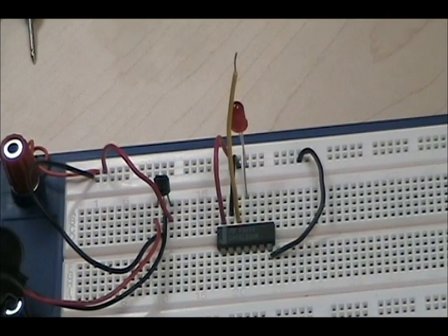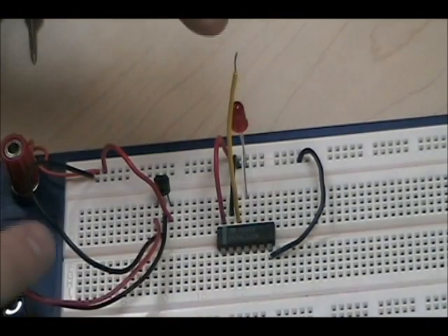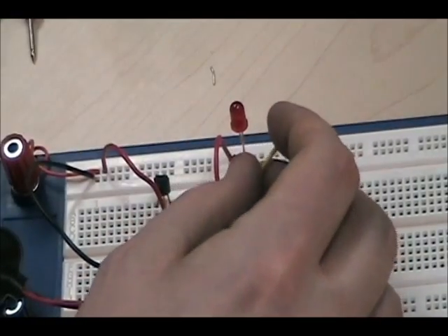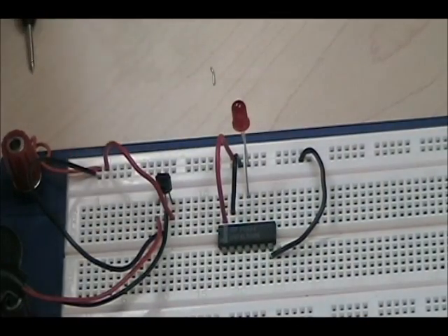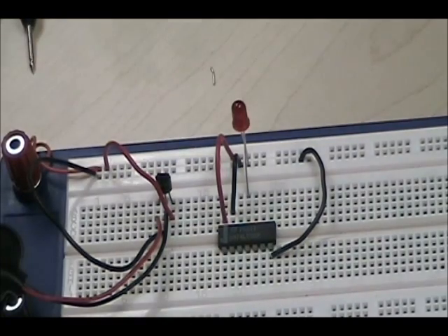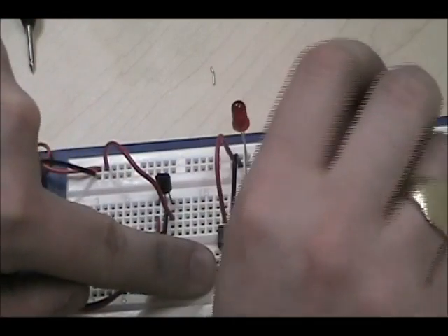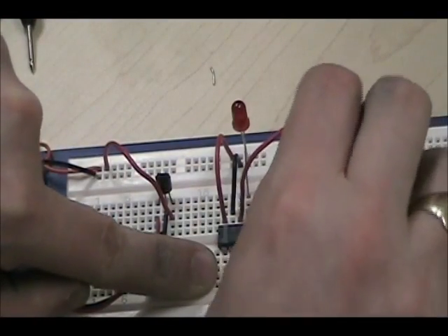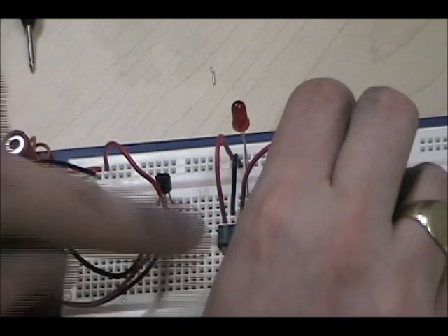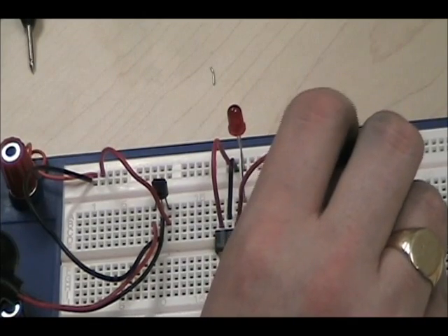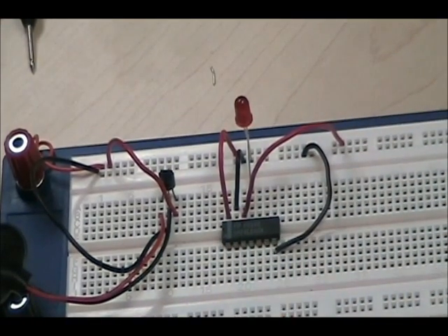Remember, one of its inputs right now is grounded. So I can take this pin right here and connect it manually to the 5-volt line. Oops. My wire fell off. Okay. Let me use another one. That's never fun when that happens. Okay, so I can connect it to either the 5-volt line or the ground line, and nothing will happen because the other input is connected to ground. So let's connect this one to our 5-volt line. So right now we've got an input at 5 volts, which is a 1, and an input connected to ground.